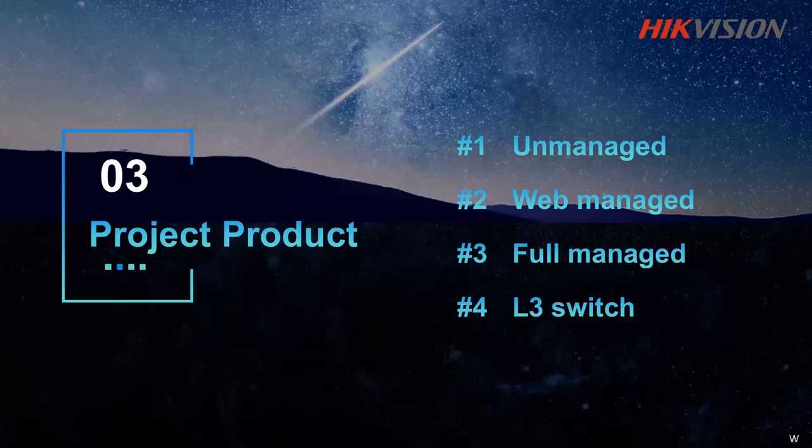So what you have to do is connect the proper earth. So when there's a high surge situation, it is not damaging the equipment, but it is diverted to the earth line. But for the NVR, for some models, I think we have the built-in surge protection, but some models do not. So definitely using a dedicated surge protector in this kind of situation would be ideal in terms of securing it against the lightning.